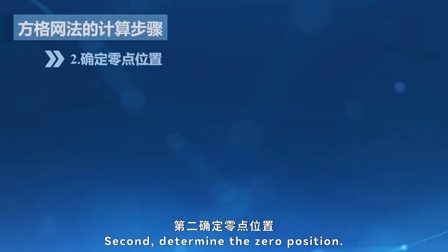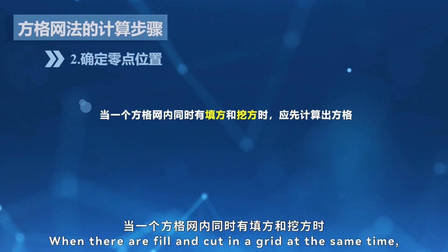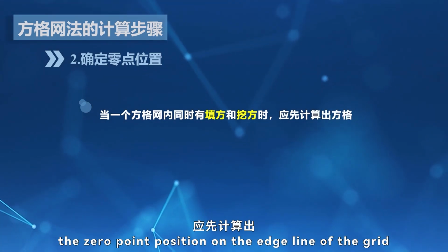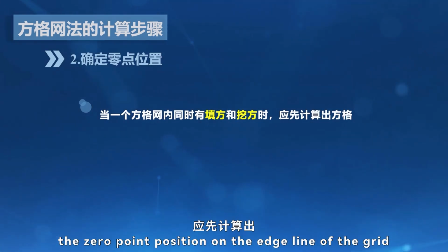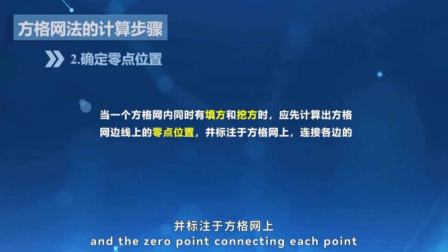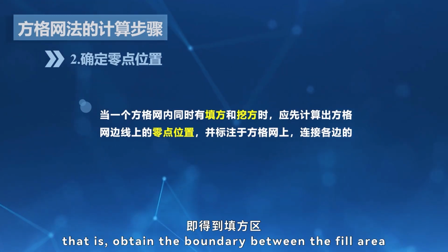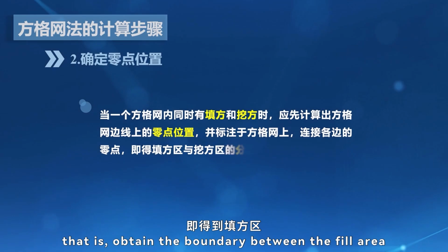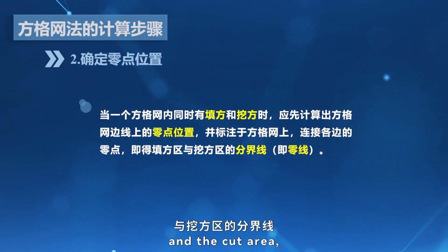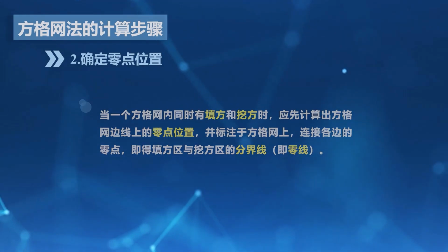Second, determine the zero position. When there are fill and cut in a grid at the same time, the 0 point position on the edge line of the grid should be calculated first, and the 0 point connecting each point should be marked on the grid. That is, obtain the boundary between the fill area and the cut area, which is the zero line.